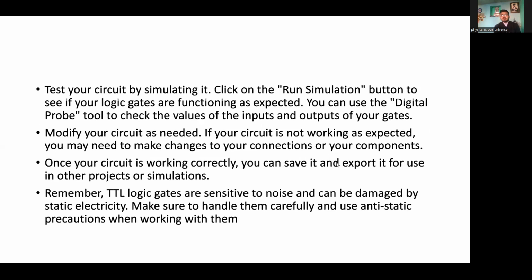The next point is to test your circuit by simulating it. Click on the run simulation button to see if your logic gates are functioning as expected. You can use the digital probe tool on the outputs of your gates, and check the values of the inputs and output values.